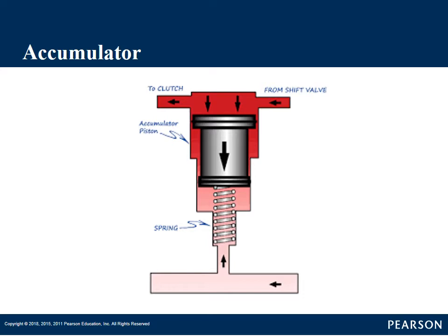Okay, and that'll almost always lead to a customer complaint. This happens a lot in transmissions with age, where the accumulator spring gets broke or wear in the transmission causes pressures not to be where they were designed to be, and you get these improper shifts. But the whole idea of an accumulator is to soften and lengthen that shift in a clutch pack.